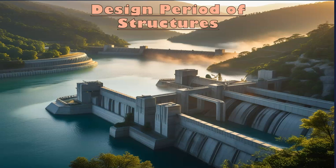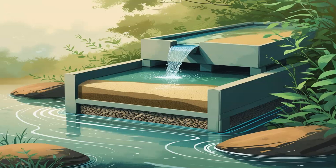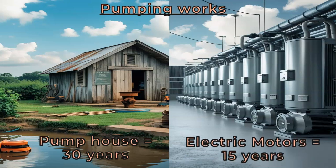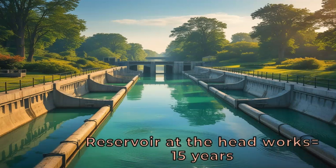What are the design periods of structures? For dams and reservoir tanks, it is 30 or 50 years. For conveying pipes or distribution system, it is 30 years. For filtration works, it is 30 years. In the case of pumping works, for the pump inside the pump house, it is 30 years, and for electric motors or electric pumps, it is 15 years. For water treatment units, it's 15 years. For the reservoir at the headworks, it is 15 years.